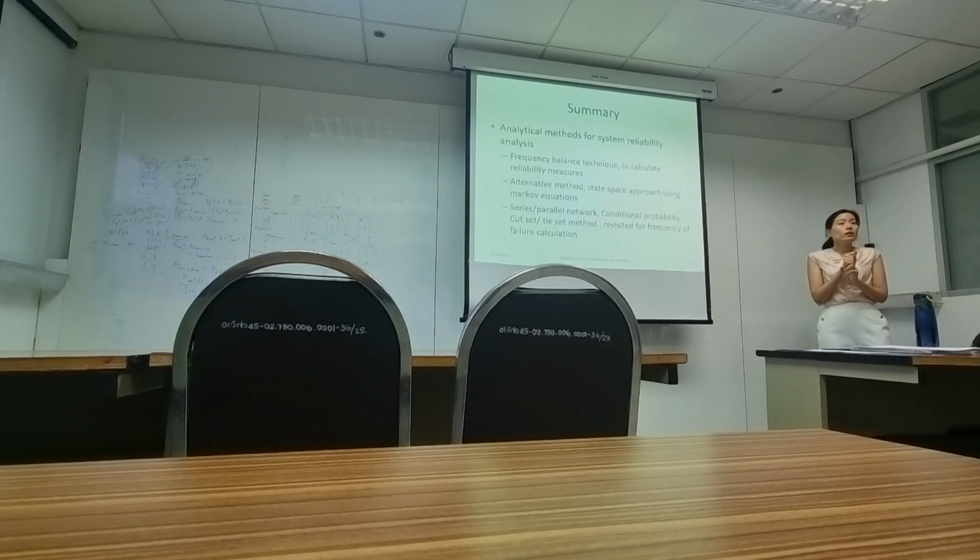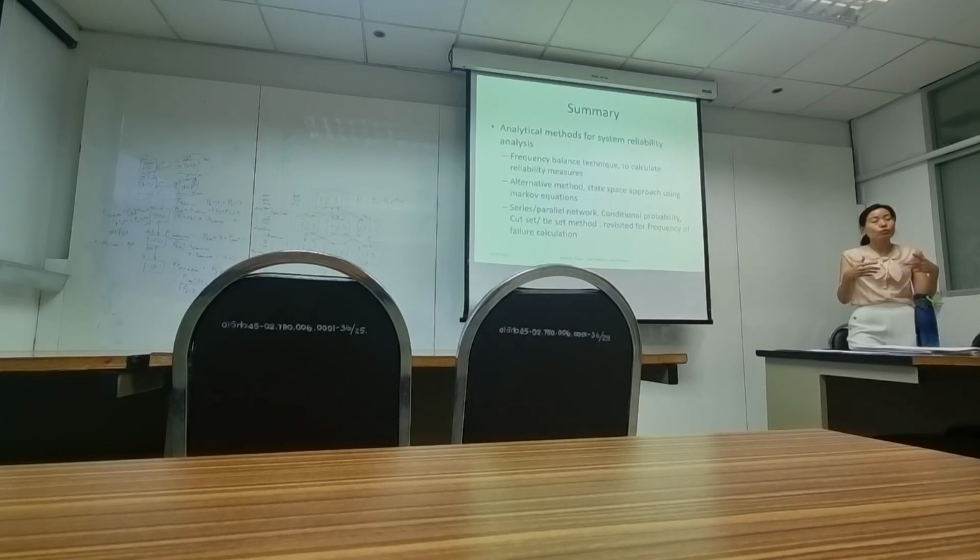For example, you might say that our system will experience loss of load only 2 hours in 1 year. You see, those 2 hours in 1 year are actually just the probability, right? But it's the other way that we use to communicate. We don't talk about probability, but we talk about the expected time. So basically it's a probability times the number of hours in 1 year.